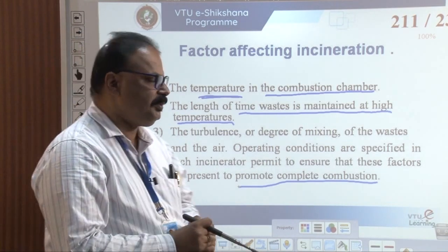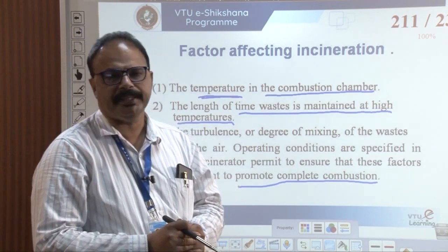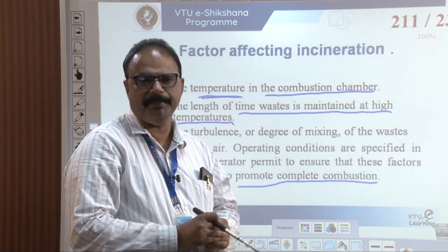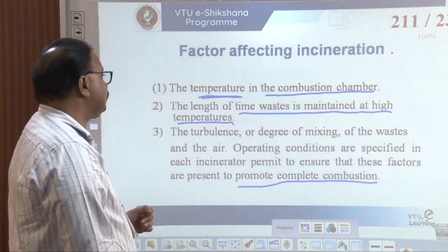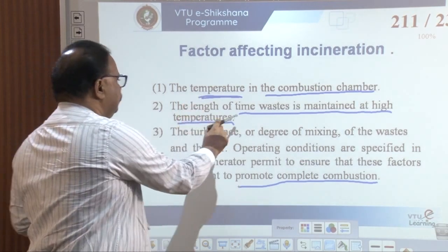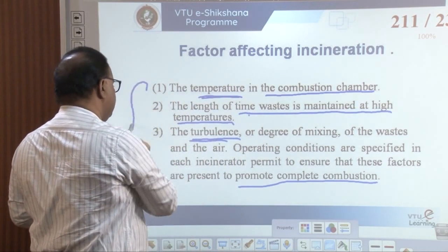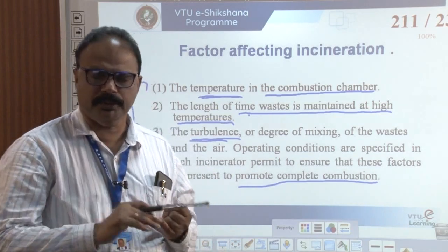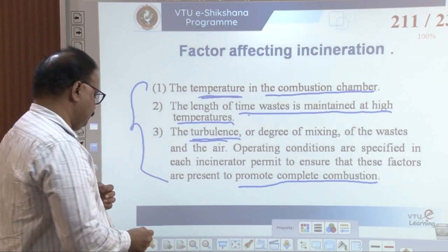Turbulence, or degree of mixing of the waste and the air. These are the main factors of incineration: temperature, time and turbulence. These are the three factors affecting the incinerator.